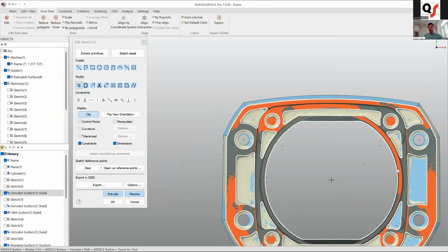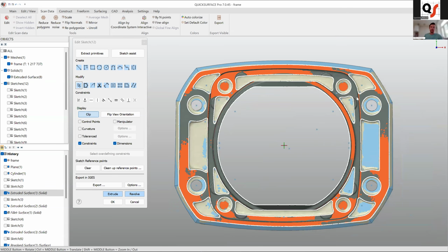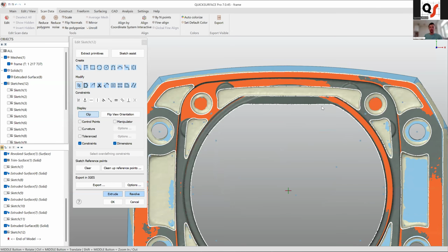So this is why you probably want to simplify this, so you create feature by feature in a separate extrude and separate sketch, so everything is visible easily, and you can actually come back to every single feature and the sketch of this feature, so you can modify it without any problems.